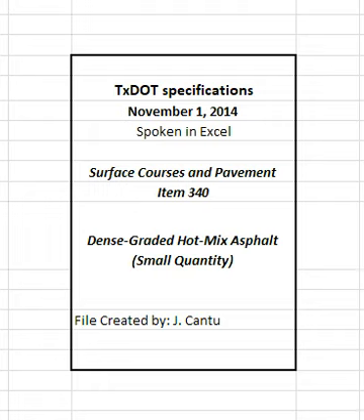4.6.1 Weather conditions. Place mixture when the roadway surface temperature is at or above 60 degrees Fahrenheit unless otherwise approved. Measure the roadway surface temperature with a handheld thermal camera or infrared thermometer. The engineer may allow mixture placement to begin before the roadway surface reaches the required temperature if conditions are such that the roadway surface will reach the required temperature within 2 hr of beginning placement operations.